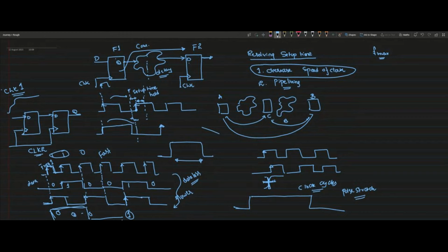For the reverse way, if I have one big pulse coming at the lower frequency and I want to capture it at higher frequency, wherever there is an edge in the receiver clock domain, I will do the edge detection and make a single pulse, and that single pulse I will detect. So this way we can pass the signaling. This is for signaling that I am saying these two techniques.